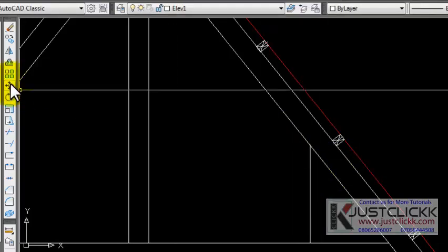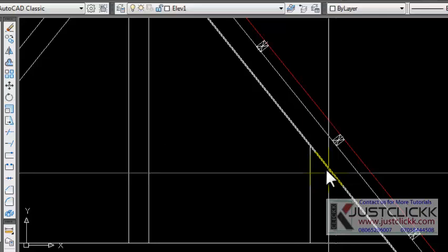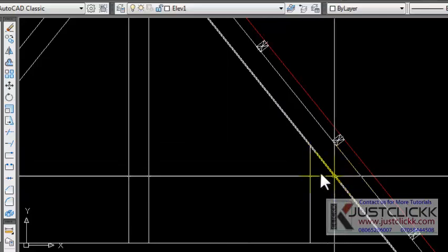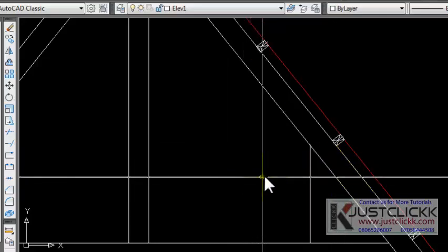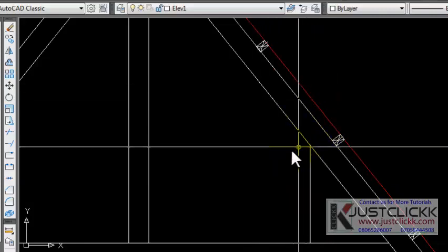You select the trim tool, and then select the object in question. Select the terminal point, press the enter key, and then the object you intend to trim, you then click it. So that's how you can trim such.